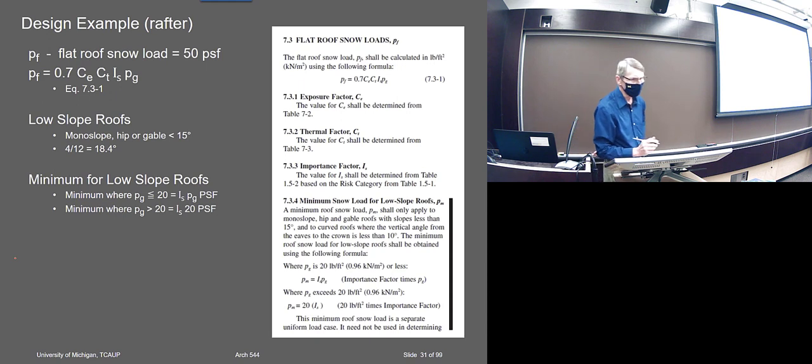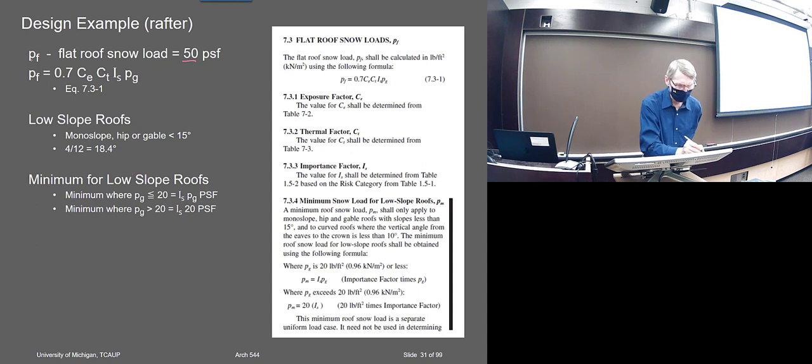Okay, and now, oh boy, the snow load. Okay, from the map, the ground snow, oh, that should have said ground snow, really. Misprint, sorry. That should be ground snow, is 50, and then to get the flat roof, we knock off 30% and multiply these factors, right? So let's see what they are.